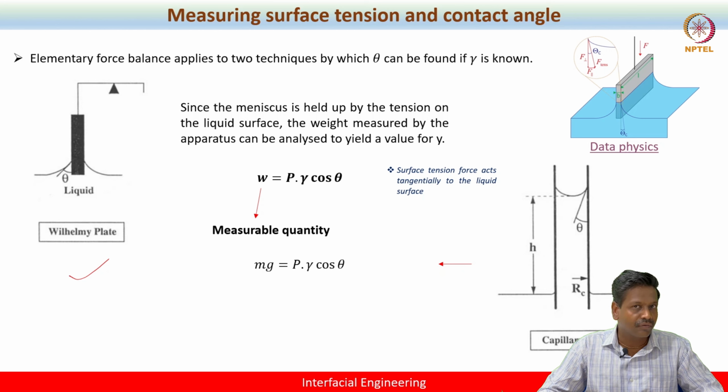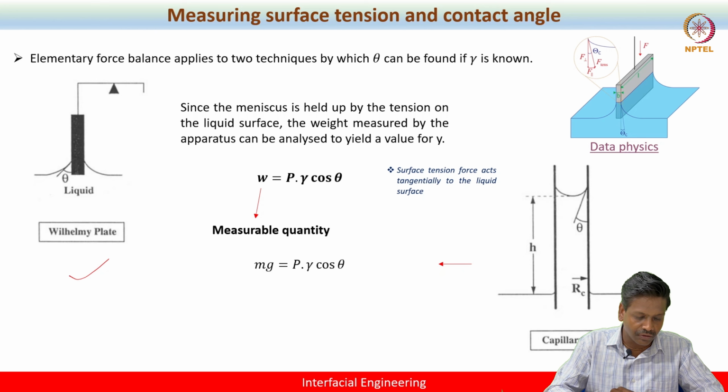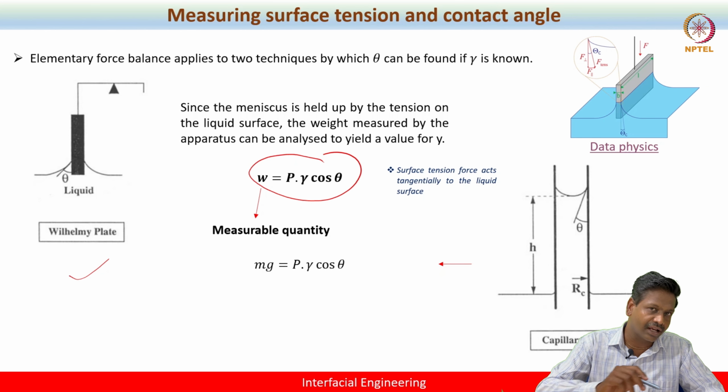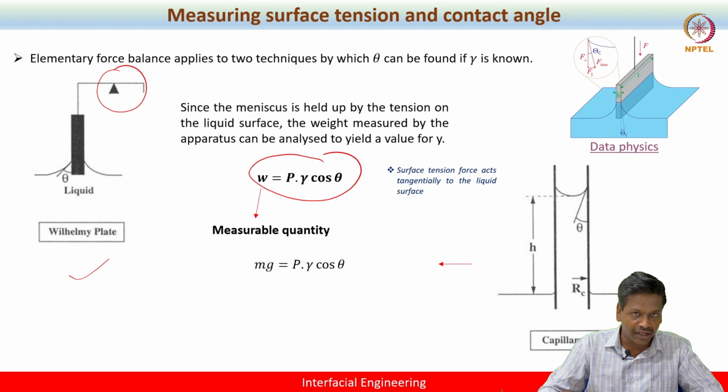So basically what we do is a simple force balance. So how it works is very simple. Whenever we introduce a plate, which is called the Wilhelmy plate, this plate is connected to what is known as a weighing balance, a very sophisticated weighing balance.